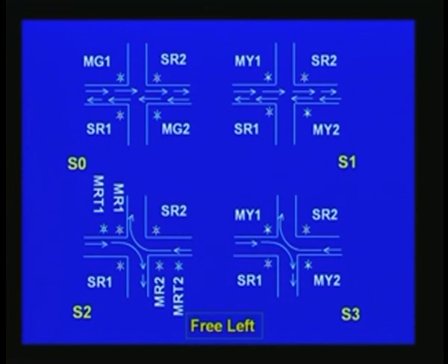It's basically a main road, and in both directions the traffic flows. The very first sequence is a green light for both directions, and there will be a red light preventing the traffic flow here. This is the main road, and it's timed for 45 seconds, which is exactly what it is in that particular junction. After 45 seconds elapse, it will go yellow for both the main roads. That means green is withdrawn, and that is the second sequence.